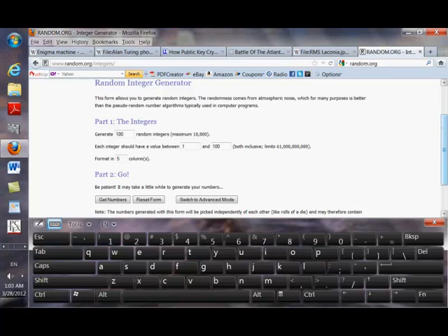Now, what is the characteristic of white noise? The characteristic of white noise is that whatever sequence you generate during a certain time window of observation is independent of what you will produce in any other non-overlapping time window of observation, and the characteristics will be exactly the same.